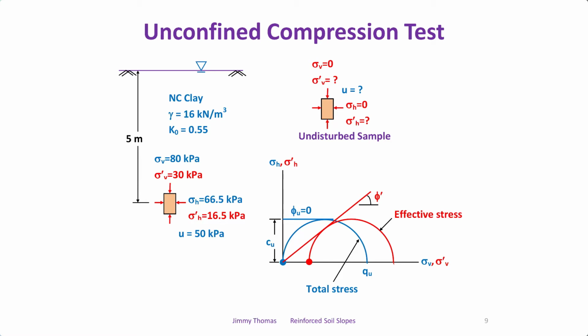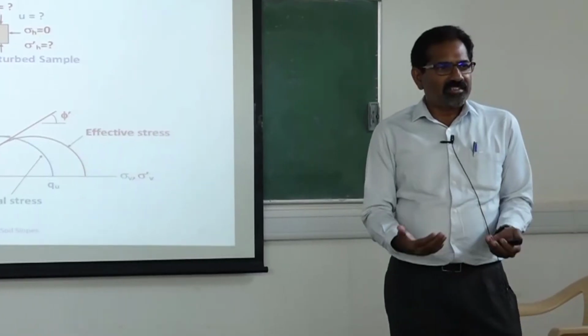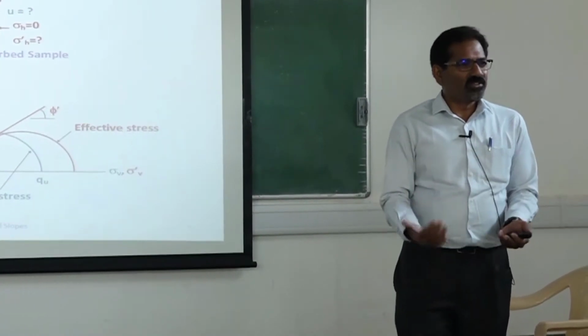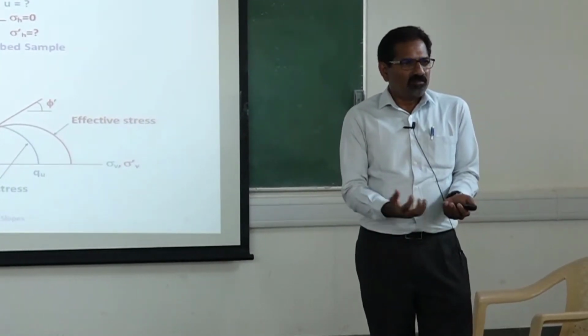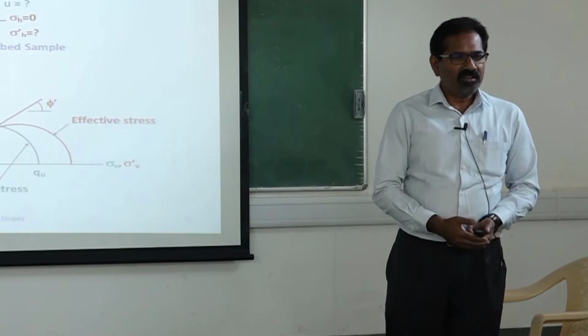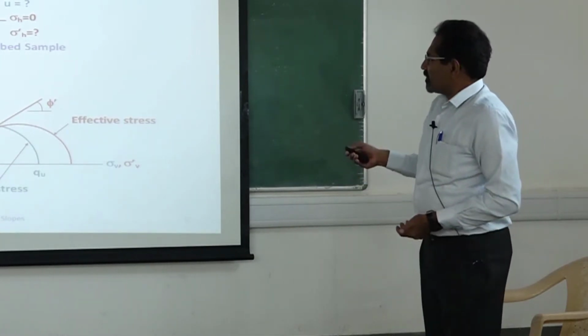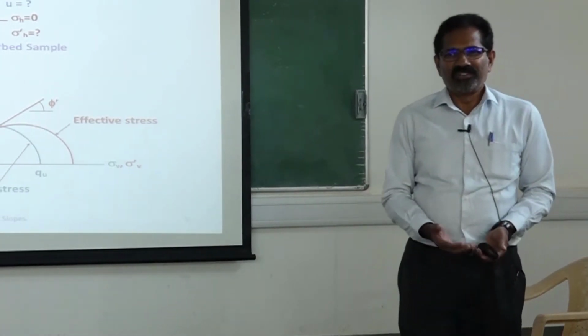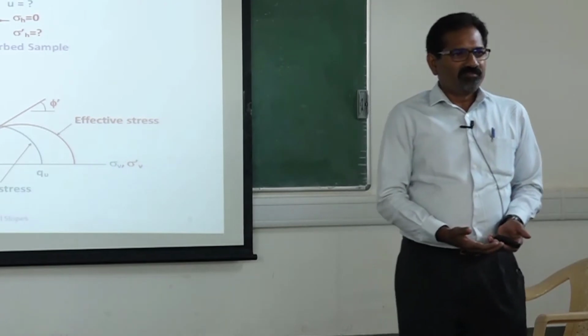So now let's assume we take a borehole, take a sample, like a tube sample, and then eject it from the sampling tube. So we get the sample. Now what are the stresses? Total stress is 0. Vertical stress, horizontal stress is 0, because the weight of the sample we can neglect. What about effective stress? We don't know. We don't know what the pore pressure is.